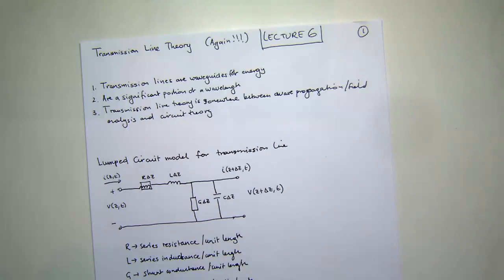Does the voltage go up instantaneously? Suppose it was even a resistor. Would it go up instantaneously? Okay. Because the speed of light tells us how fast the signal can go from one point to the other. And if that transmission line is a significant portion of a wavelength, it takes a finite amount of time to get from one location to the other.